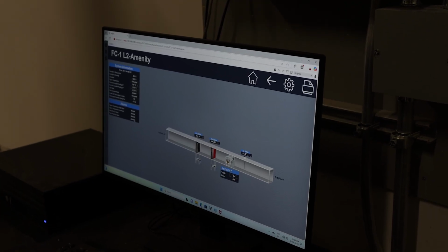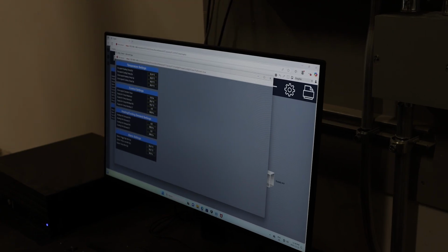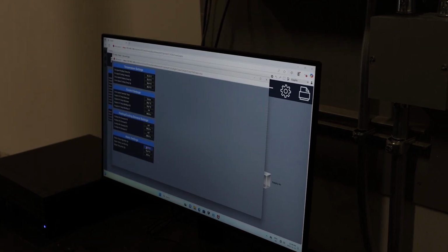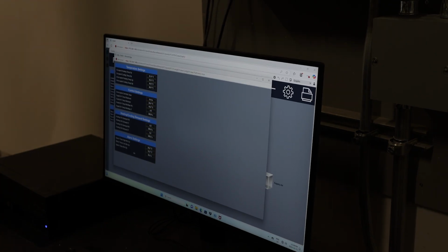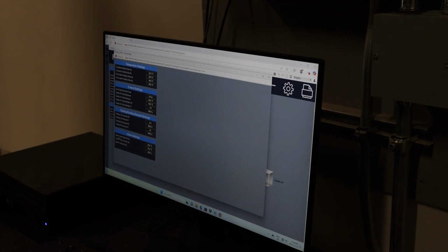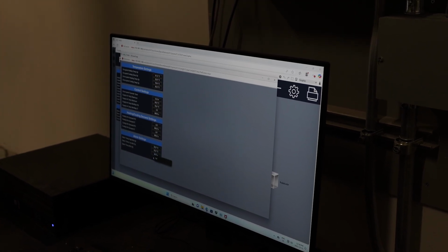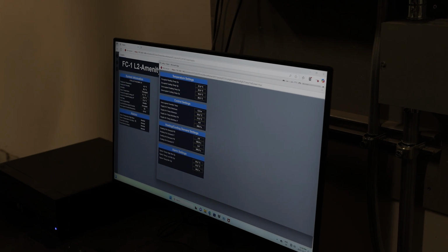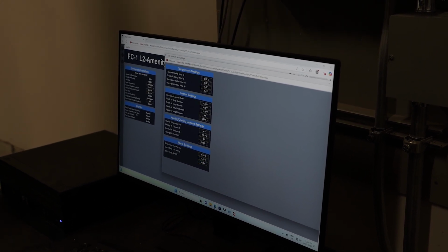That's why we have those two alarms and the space temperature alarms. In the alarm settings, space temperature high alarm set point is 30. Space temperature low alarm set point is 15. Space temperature alarm delay is 30 seconds. So when space temperature is above 30 for more than 30 seconds, we would see this alarm. If the space temperature is lower than 15 for more than 30 seconds, we will see this alarm.